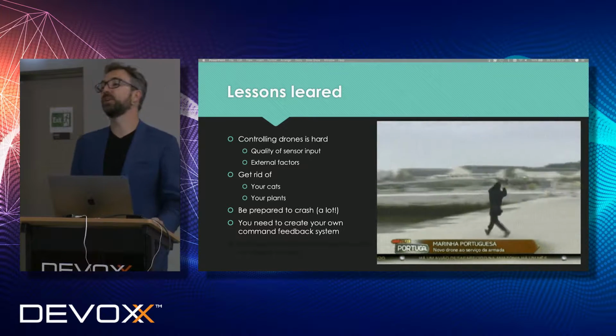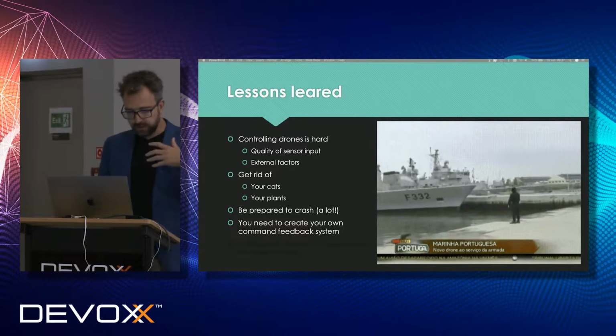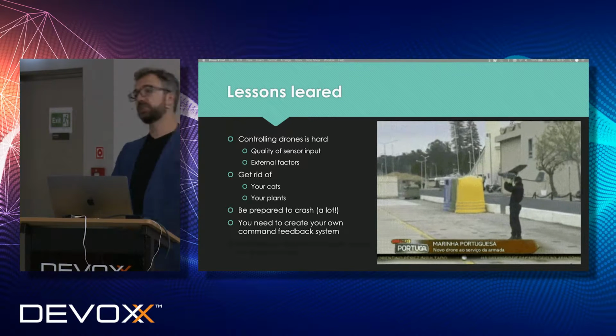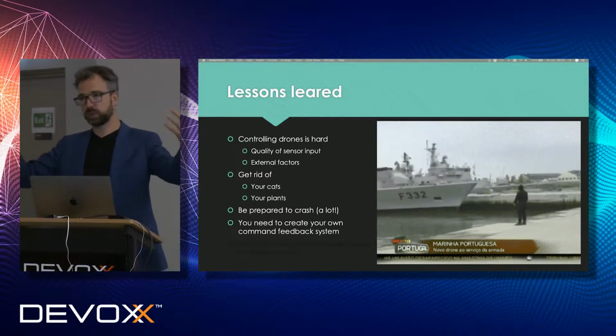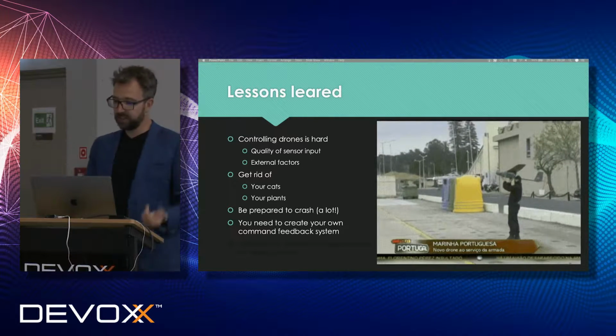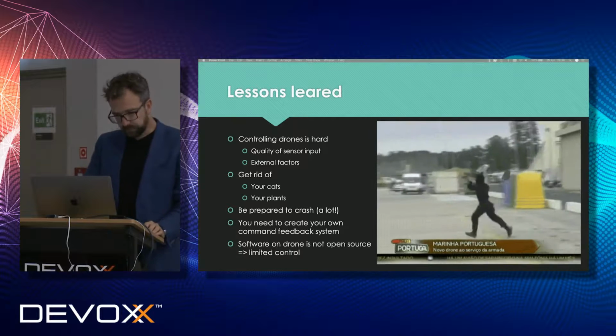You need to create your own coordinate feedback system, or command feedback system. Because this is UDP, this is maybe the most tricky part also, that you kind of have this dance where stuff is coming in and you're sending it out. And yeah, it's no TCP.